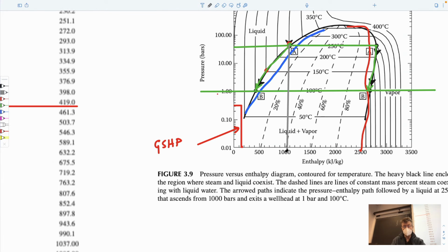So we know that when it's in the ground, it's at something like 1,000 plus kilojoules per kilogram at this particular point. As we bring it into the system, we're going to end up at this point, because by definition, if it's initially at this state and we don't allow it to change its enthalpy, it has to come out and have this amount of energy associated with it. And I guess what we don't know is what it would look like. Is it going to be water, or is it going to be steam?